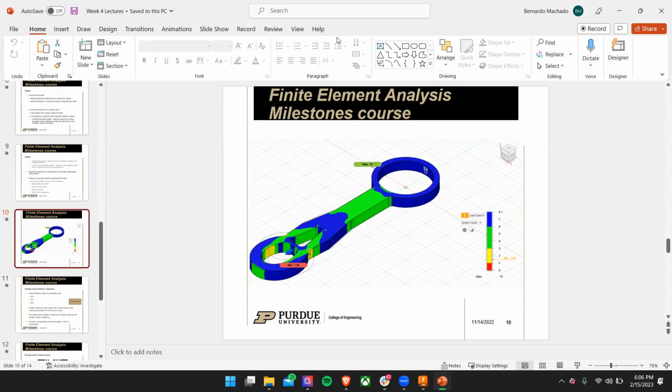Could you do the lines, you just extrude the form? Go ahead and extrude. Or, sorry, wait. When you sketch, you need to sketch the part that you're going to remove. So you sketch that inner circle, the black one. Yeah, so you're going to want to sketch from the big outer one.